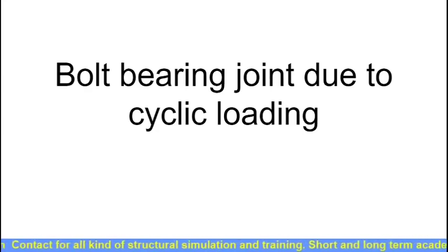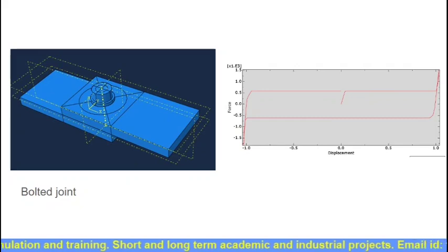Today we are going to discuss the simulation for bolt bearing joint due to cyclic loading. We are going to create this bolted joint in Abaqus and we'll be generating this force displacement curve, which you can see. This force displacement curve is generated due to cyclic loading.